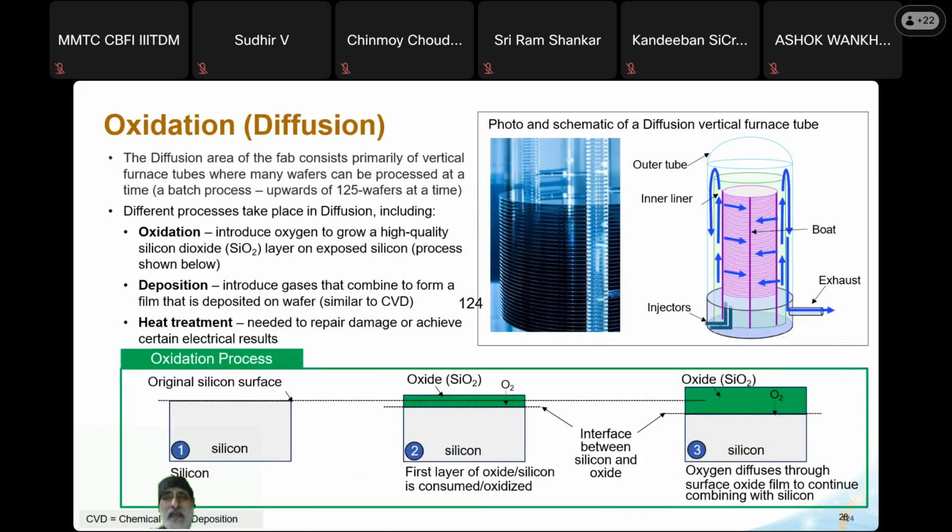And so this is how to deposit oxidation and things like that. You see here, there is a difference between oxidation and growing. So here we are growing because this is a silicon surface. When it reacts with oxygen, some of the silicon atoms here are consumed. So you can see here this level. So this much, 40% is of the silicon atoms converted into SiO2, and 60% is on top of it.